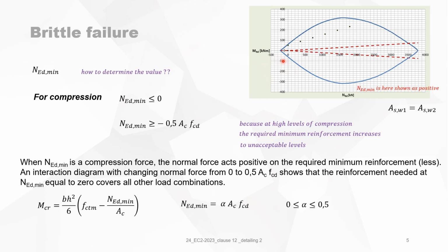And you see for a chosen value of reinforcement, you get this interaction diagram, and I've plotted all the combinations, like stated here, with alpha from 0 to 0.5, which are those green dots. Normally, in each green dot I should have an interaction diagram, but I've left this out of the picture, otherwise you will not see a lot.